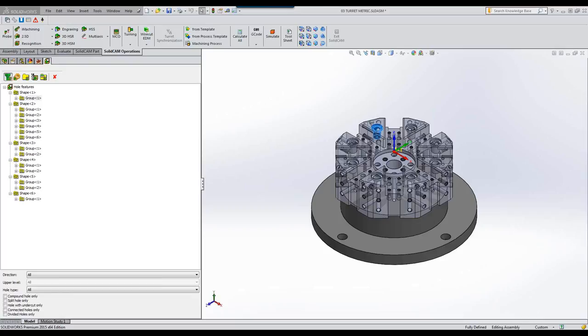It is not, however, aware of the stock conditions. Now remember, these are 2.5D operations. In any case, these are still 2.5D operations. Okay, a good question here was also, if 2 holes cross each other, the hole recognition recognizes the continuation of a hole through the next hole, and it will see that as one hole going through, and the same thing with the hole coming from the other side as well. So it'll recognize still the entire hole in its entirety.